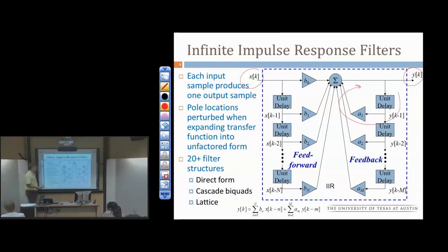So we limit it, either a single precision float or 16-bit int or 64-bit float. So we're always going to get truncation here as a result of the multiplication and the addition, and this is going to introduce quantization error. That's just a limitation in IIR filters. Once we implement this, we can rarely keep the LTI property because of this. Also, separately from that, just to represent the feedback coefficients, we run into trouble pretty quickly.